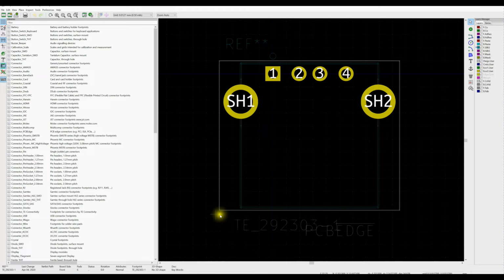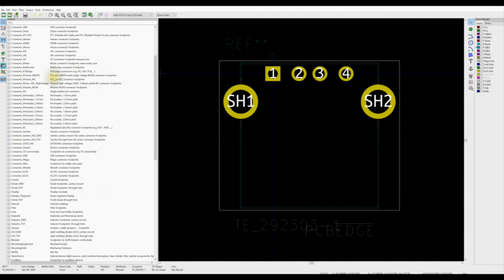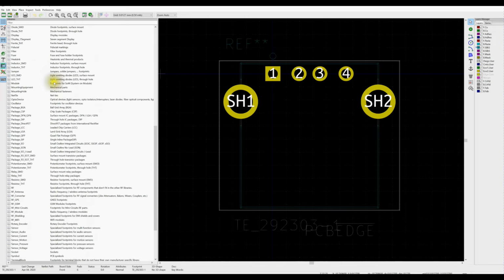The edge of the printed circuit board will be down here. It's got the 2 places to connect grounds. It's got the 4 pins, and something you're going to want to validate as you work through this, that the footprint and the pin numbers are correctly oriented, so that when you add a part in the actual spreadsheet or the schematic designer, those actually line up and make sense. So the question becomes, where did it import this at?